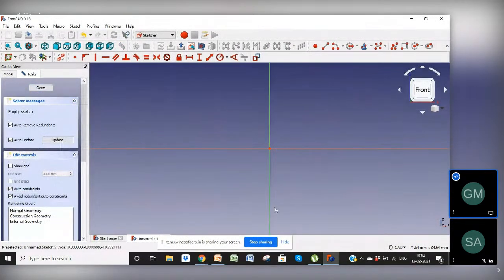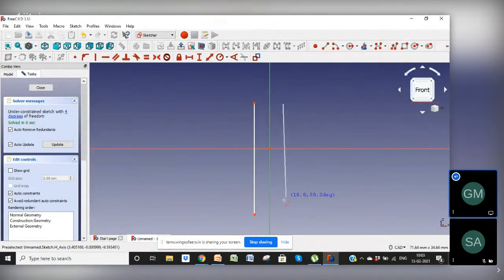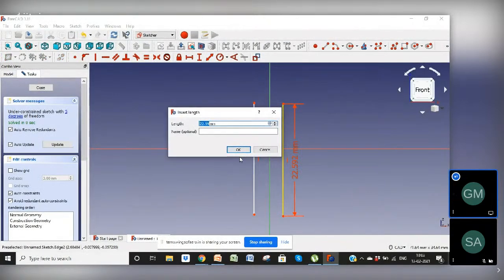Okay, here we go. We are going to make drag strut 1 first. For that I am taking this vertical line 1 and 2. Okay, making them vertical, both of them. This is vertical, vertical, making both of them equal. Okay, now let's give a dimension to one of these. Making drag strut 1, it would be longer. Let it be 100 mm.